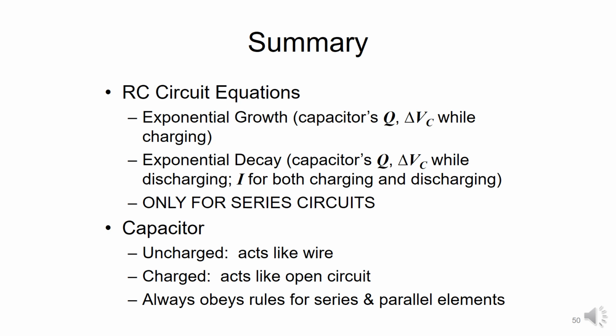All right, so that's our summary. For RC circuit equations, you can have exponential growth for the voltage and charge when the capacitor is charging, and you can have exponential decay for the voltage and the charge when discharging. And either way, charging or discharging, current will have an exponential decay. And reminder, this only applies when resistor and capacitor are in series. If they're in parallel, then it doesn't apply.